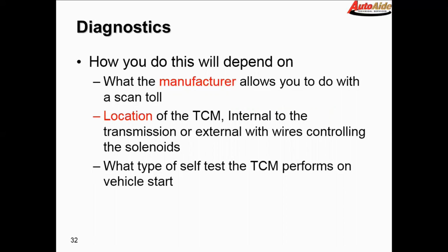And unfortunately, a lot of the valve bodies now are incorporating the TCMs into them. So the valve body still has spool valves, but it now has all the solenoids and the TCM all internal to the transmission. So getting at the wires that run to the solenoids is a little bit more difficult than going through a bulkhead connector now.